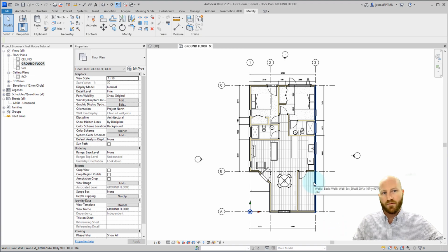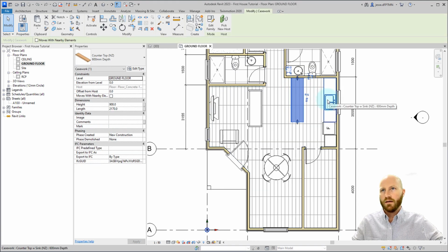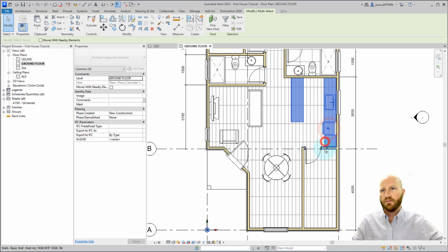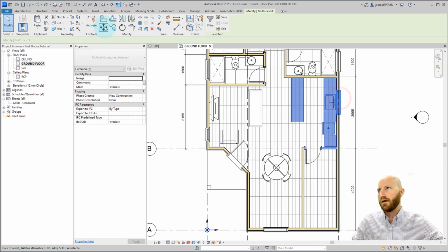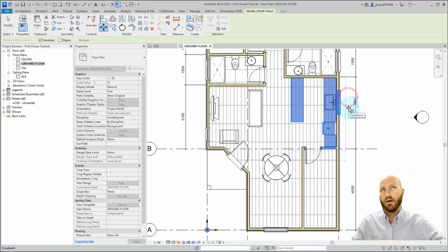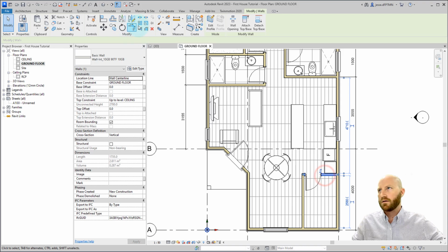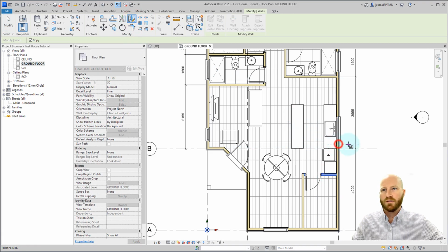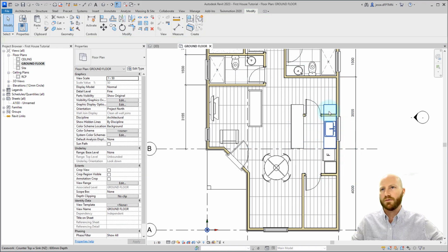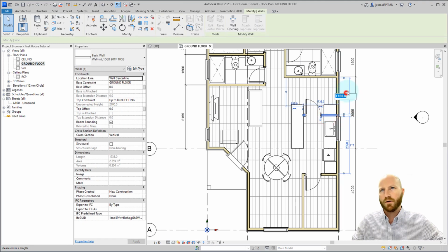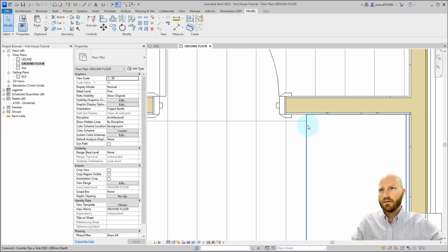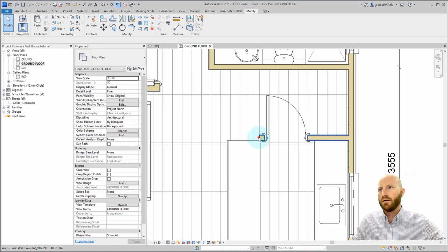All right, let's modify the inside of the house. Let's grab everything in the kitchen, including this wall and that, and let's move this down by, I want to say 1310. And now click on this and let's mirror this just a rough amount, because what we'll do is we'll use our temporary dimensions here to make that 1200. And those lines worked out really well.